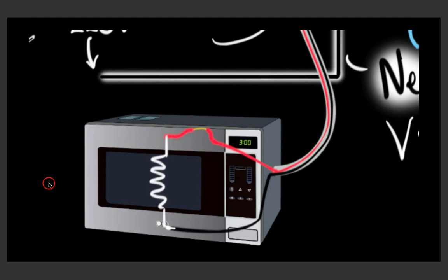So the ground wire basically is a safety. If electricity is flowing through the ground wire, that means that something has gone wrong. And the ground wire basically makes it so that you don't get shocked, or you shouldn't get shocked if something goes wrong with the wiring in the device. So this is showing our live wire breaking apart so that the wire is exposed, and that exposed wire is now making contact with the metal casing of the microwave.